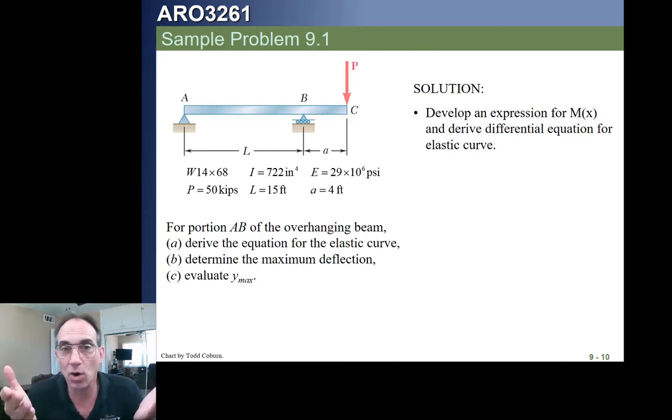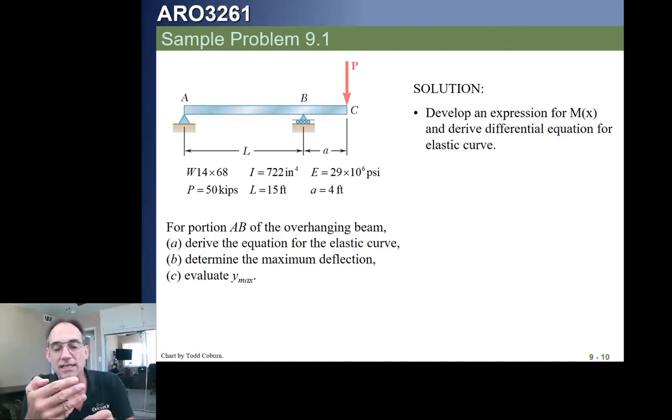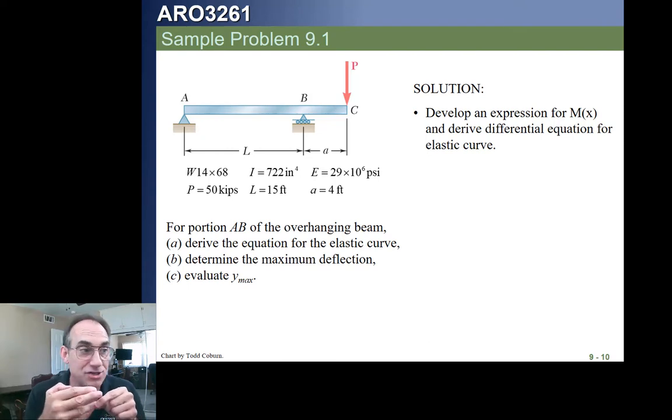But that's nonsensical work because actually, in this process, we already know what the derivative of the deflection is, and that's the slope. You already have the slope equation, so you can just take the slope equation, set it equal to 0, and that will tell you the locations where you might have a maximum deflection. You can look at the different ones and grab the one that's maximum.